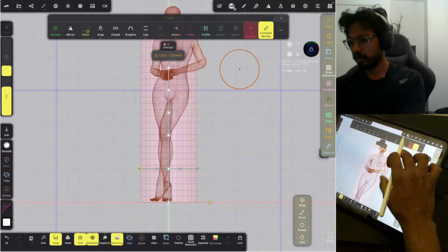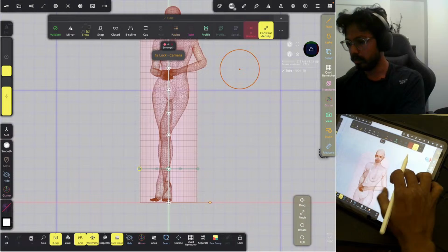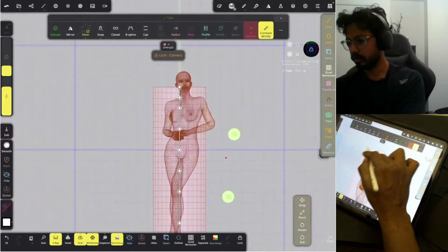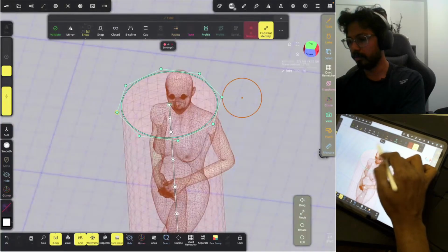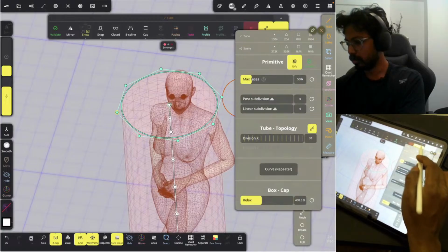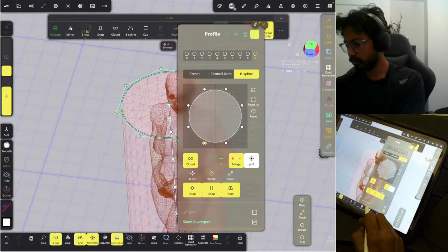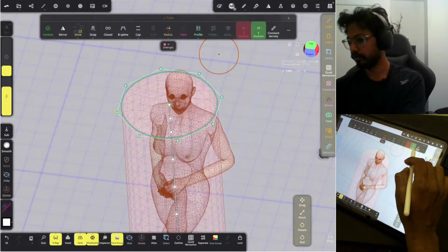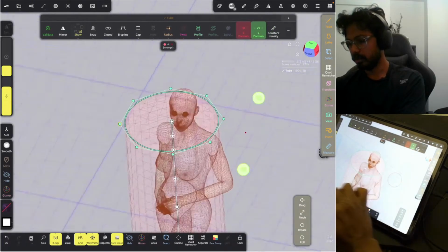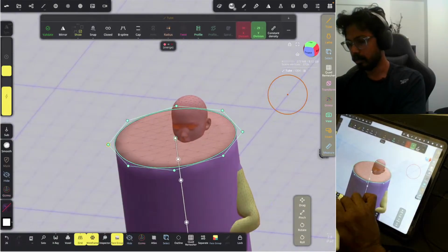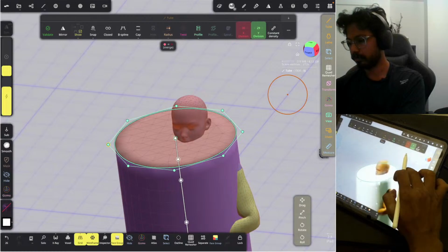The profile at the top can still be circular, but to have this profile visible, you can switch on this show in viewport. That will help you. Switching off the X-ray mode, I'm going to hide the face groups, and I'm going to hide the caps as well.